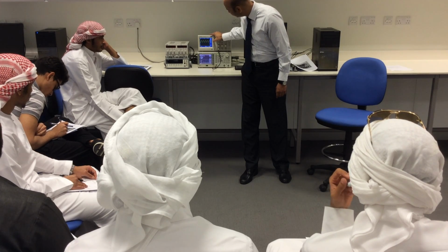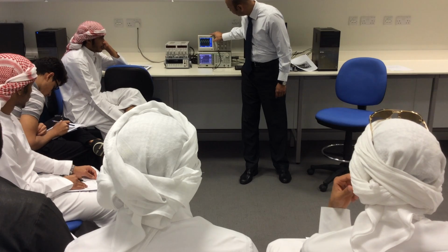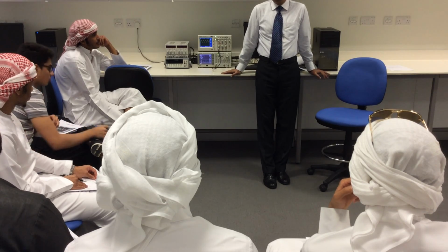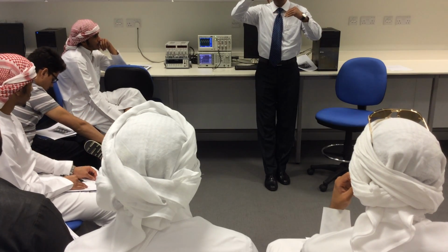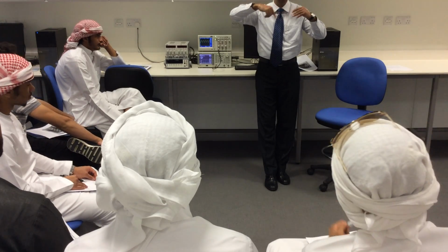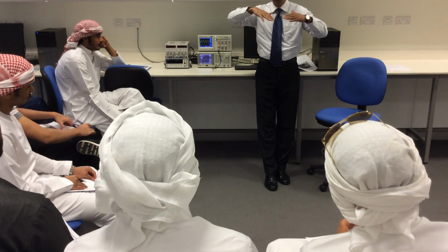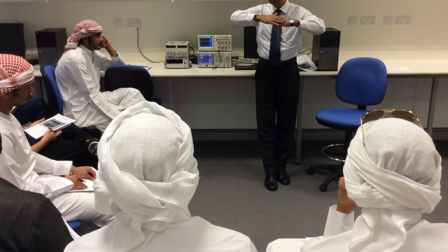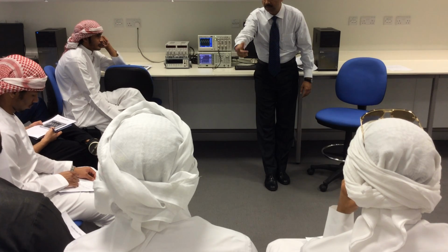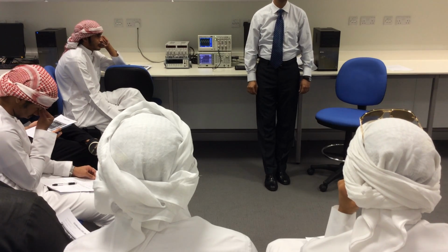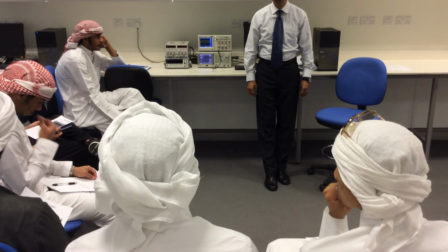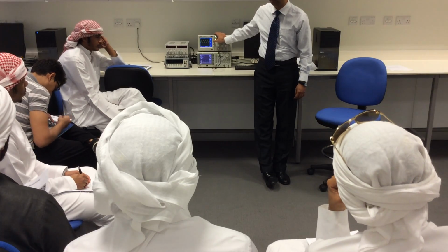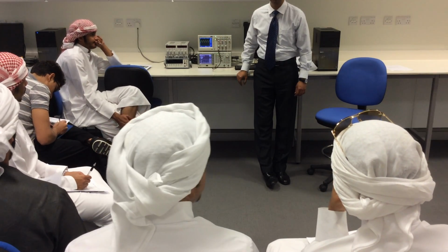Mean is the average, which is about 5 millivolt. By the way, what is mean? Average. But if you have a pure AC signal, the mean should be 0, because plus and minus should cancel to 0. So the mean will be, what did you say? DC offset. Okay. So using this equipment, you can select the value which you want to measure, and you can measure different parameters.